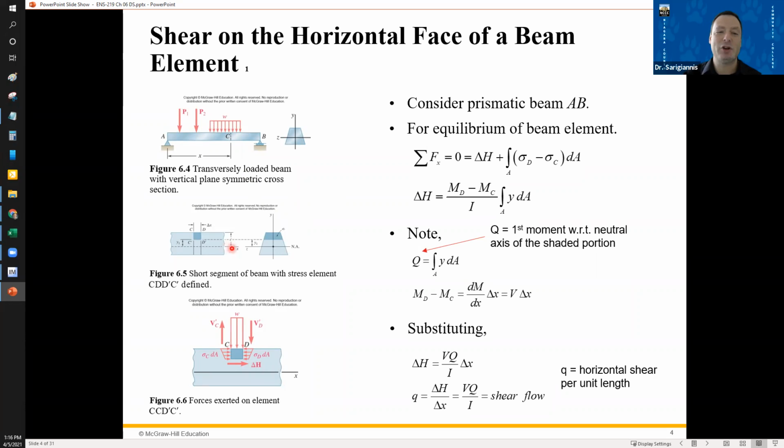This height from the neutral axis, so notice this is the neutral axis of this trapezoid. From the neutral axis, you have a height C, which takes you all the way up to the top surface. But you also have this height, Y1. I should have blown that up for my old eyes. Y1 is the height at the bottom of this little portion that you're looking at, above the neutral axis. And we have this little area A. So let's go through some of these formulas.